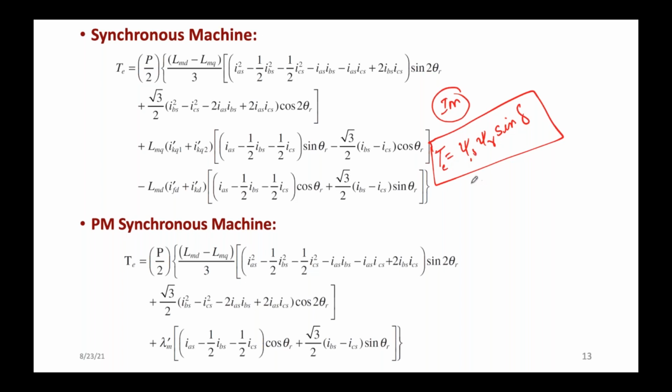With respect to the stator side, there are three state variables: A phase stator flux, B phase stator flux, C phase stator flux. With respect to the rotor side, again three state variables are involved in Zr. Because of the interaction of the A, B, C phases, you get the resultant stator flux. Similarly for the rotor side, the A, B, C rotor flux interaction gives the resultant rotor flux. So finally, 3 plus 3 plus 1.